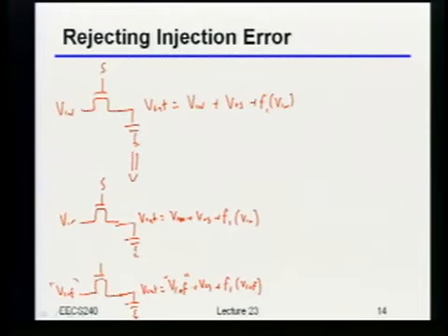Well, so how would I get rid of that offset? What should I take as my output voltage? Yeah, the difference, right? So in other words, if I just look at the difference between that one and that one, then what I'll end up with is something like V in. And by the way, I'm just going to replace this Vref with V in minus now. And that V in with V in plus.